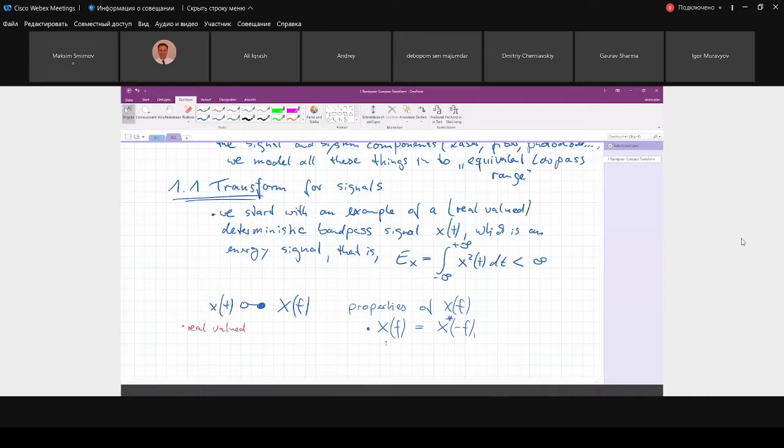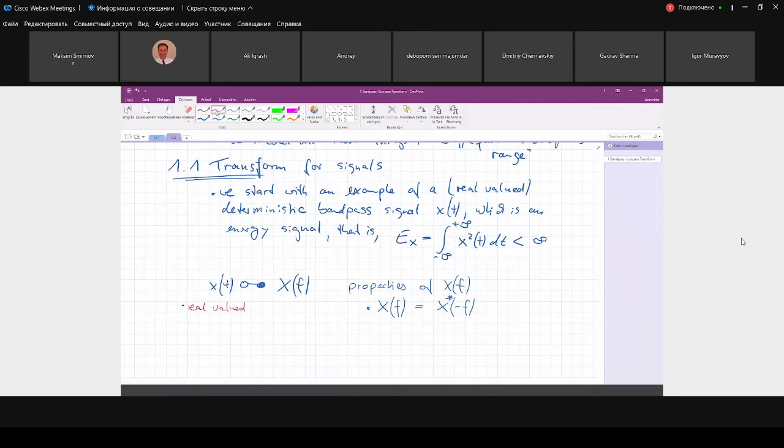And of course, we use a two-sided Fourier transform. So if we decompose our signals into harmonic waves, we use complex waves. There are always pairs of these frequencies. One complex wave has a frequency, let's say f, and it's never alone. There needs to be another wave which has a frequency minus f. They belong together. Therefore, in order to obtain a real valued time domain signal, the weightings of these complex oscillations need to be complex conjugated. And then you can say, okay, what does it mean?